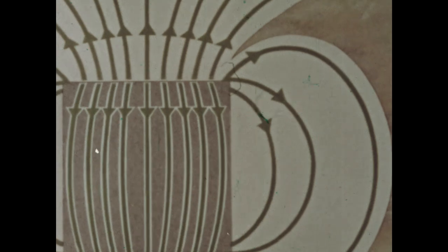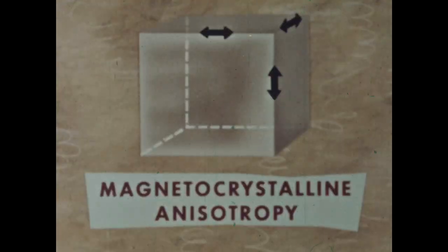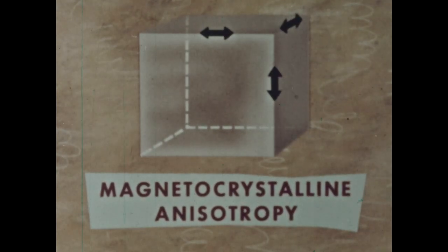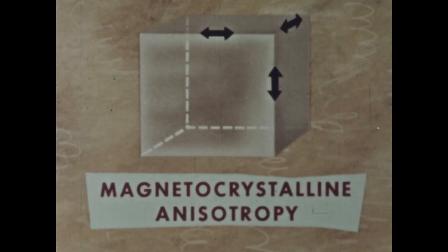An H field is present whenever there is a discontinuity in the normal component of magnetization across a surface. The magnetocrystalline anisotropy energy is a minimum when the magnetization is along certain preferred directions called axes of easy magnetization. In the cubic structure of iron, there are three easy axes.